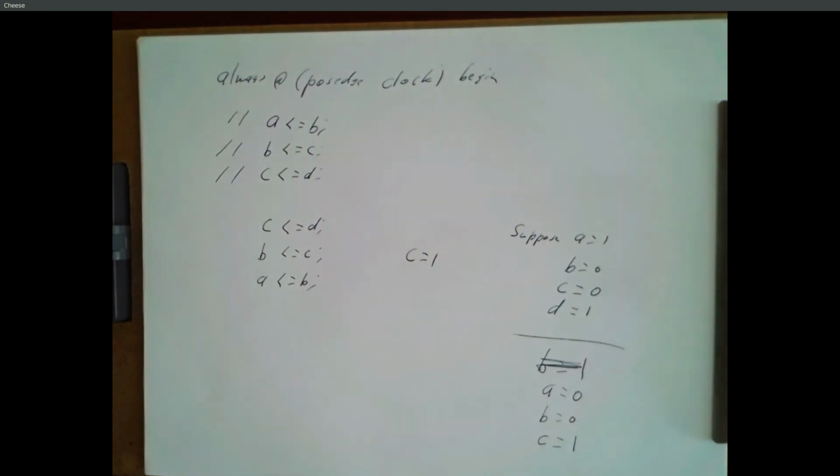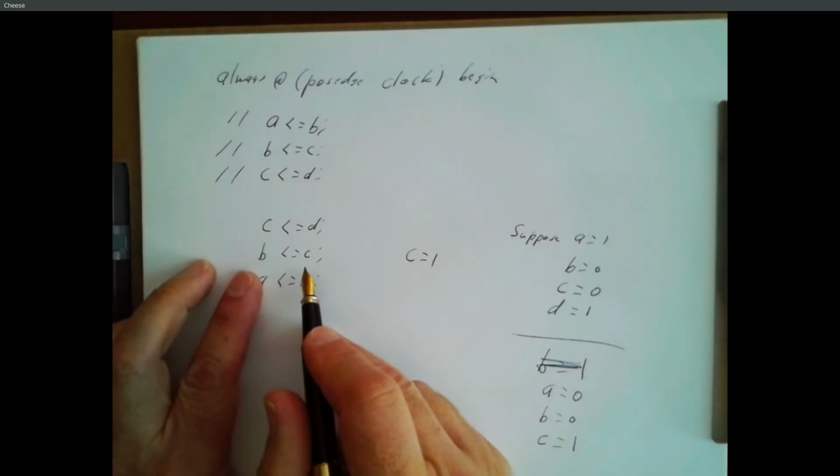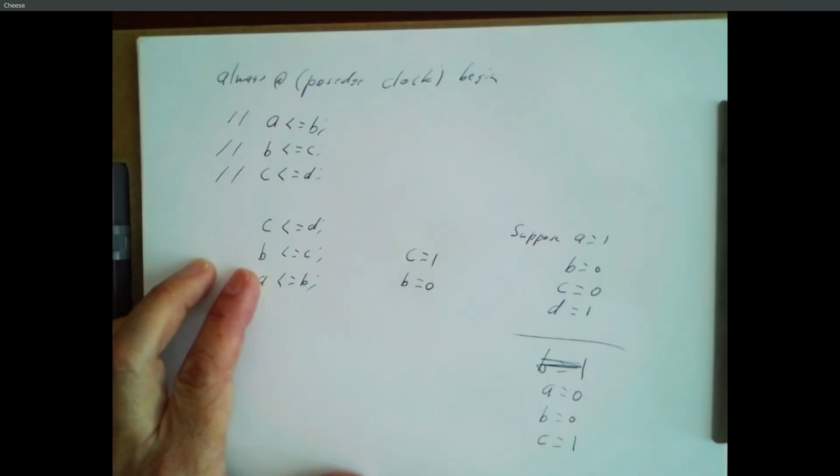What value is B going to get? It's a trick question. It's the current value that you have for C, the initial value of C. So remember, this all happens in parallel. At the same time that C is being given a 1, B is given the value that C currently has. C is equal to a 0, so B is going to be assigned that value of 0.